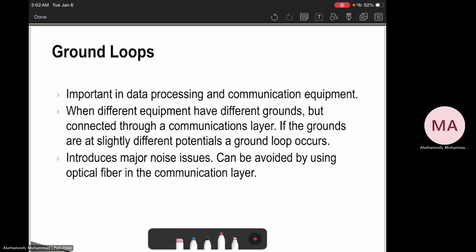Now connect these two devices with a copper communication cable, where the shield or reference conductor is attached to the ground at both ends, and circulating currents flow into the loop. Those circulating currents create what we call a ground loop. That ground loop can cause communication errors, random resets, and corrupted data. It can impact the cameras in the building, the Ethernet cable, and other things. So this can create a big problem.